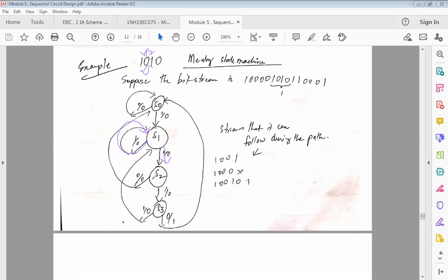So here I got 1. Now see this case. In this case, if it is 0, I cannot be in the same state, because I can look for 1 even here. Because I'm getting 1 here. Yes or no? So what I have to do is go back to state S0. See, it is like this. I got 1 0 here, so I'm happy that I have finished 50% of my detection of the stream. But still I have to receive 1 0, but that's not happening, right? I'm getting 0 0 here. So I will again go back to my first state, and again check if those bits I am getting here. I am not getting, so I will move forward. And here, at this point I'm getting, so I will mark it as 1.